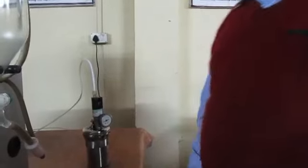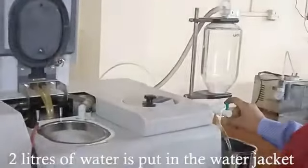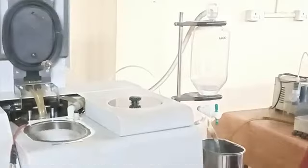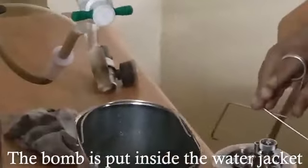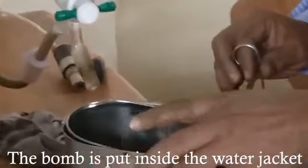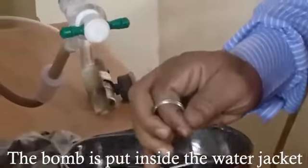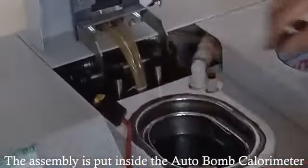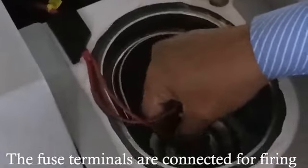The oxygen cylinder knob connecting the bomb is opened and the pressure is set to 420 psi. The water jacket is filled up to 2 liters of distilled water. The combustion vessel is placed in the jacket and then the jacket is placed in the bomb calorimeter. The terminals are then connected to the combustion vessel and covered.